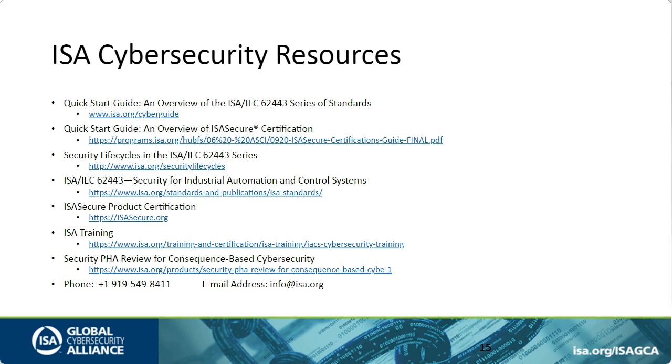So as far as I'm aware, it's not a requirement to have that role in the ISA IEC 62443 standards, but I would recommend that there is a single person that is responsible for coordinating the activities, probably in a large organization at multiple levels. You'll want to have a manager that's responsible at each local facility, and also someone higher up in the organization that is able to set policy and procedure and the standards that will be used. So it's not a requirement, but I would recommend that.